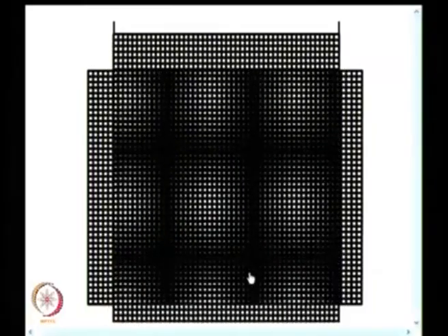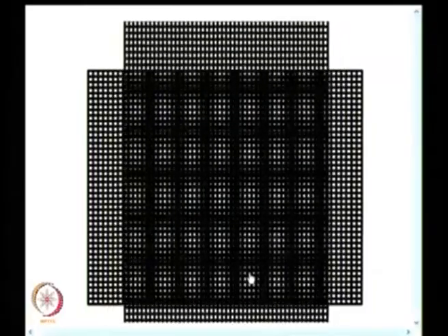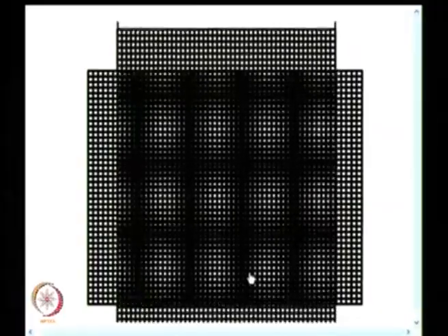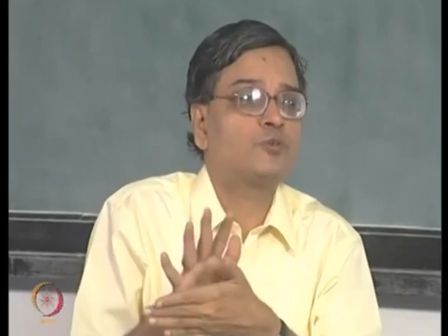And strain is a tensor, once I get displacement information I can also find out the slope, that is nothing but the strain. And if I want the strain tensor, I need three pieces of information. People have also developed a grid at 45 degrees superimposed over that. And I also caution, experimentalists, when they develop the technique, they develop it and see what maximum information you can get out of it.